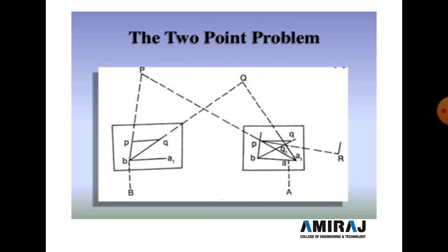First we mark the points A and B on the ground with wooden pegs. Then fix the plane table on point B. Clear? First leveling, then centering and orientation are required. From point B bisect the point A and draw the line BA.